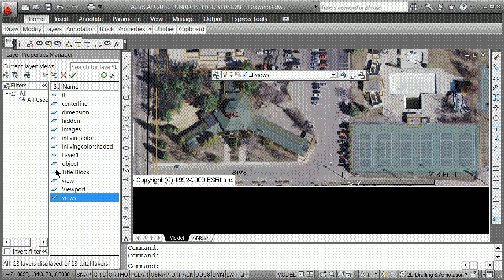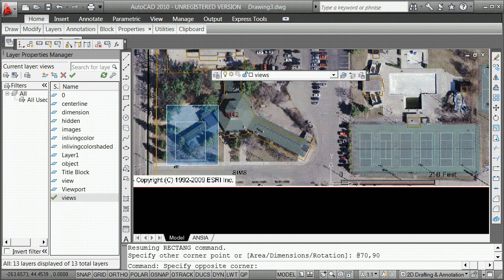I'm going to double click here. I'm going to actually start using the line weight when we get going soon, but I'm not going to do that here. I'm going to go ahead and draft a box that makes some sense on my 7x9 paper. So I'm going to try to do a box at 70, 90. Now that's 70, 90. I could have gone 90, 70.